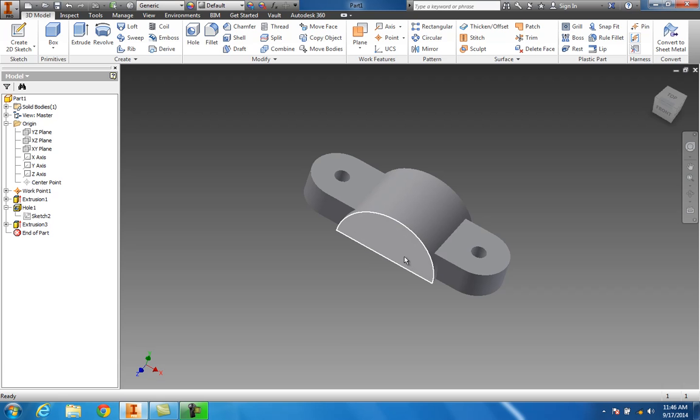So now this thing has 2 different types of holes going through this. Looks like a lemon or orange slice right here. One of them's going to be a square cut through, and one of them's just going to be a round cut through. And the reason that we're going to do this is just to show you, if you work for a company and you have to do a revision on something, you can have both of the different styles in here. It's all about just suppressing the feature, and I'll show you that.